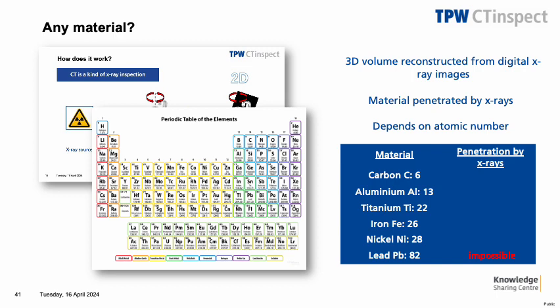As a generally applicable principle, the penetration by X-rays is better for materials with low atomic numbers. Plastics are based on carbon polymers, and these can be CT scanned very well. It is very important to mention that this relationship is not linear, but that the atomic number affects the X-ray attenuation exponentially to the 4th power.